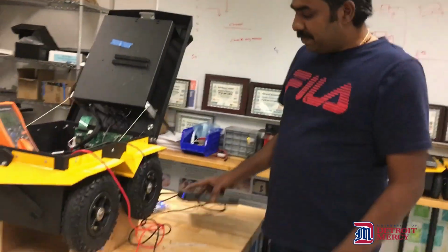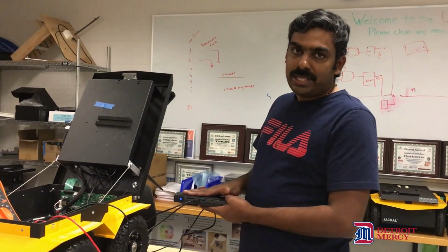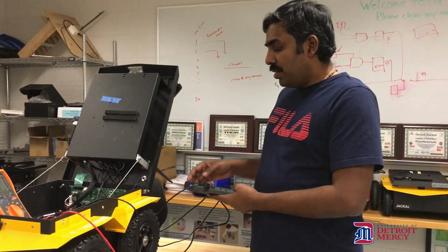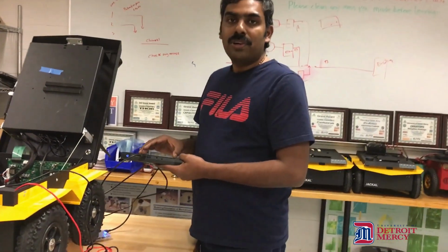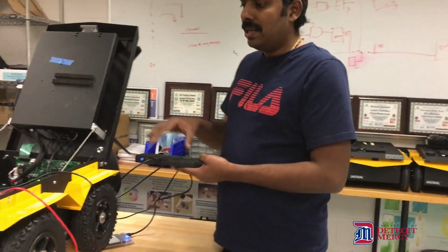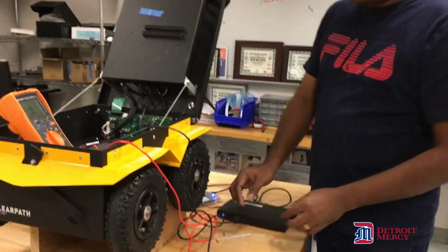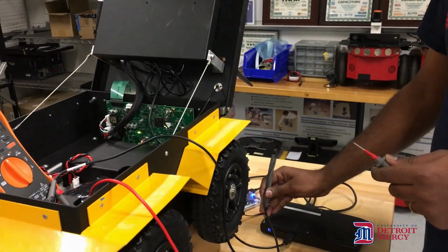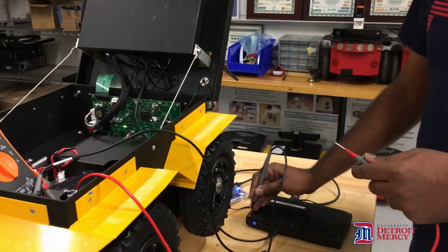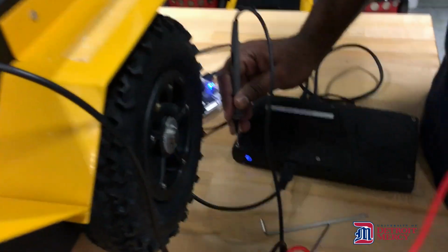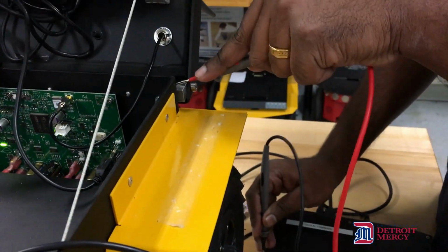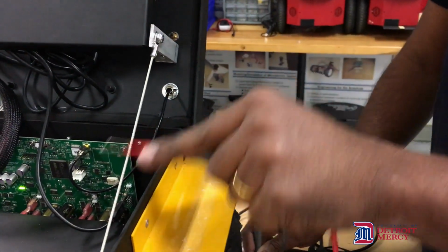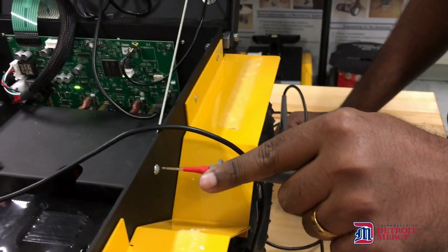So as Karthika explained, this is the NUC computer that we used. In some cases, it can be your laptop. So if you see, there is no common ground between this NUC and the Jackal. I can show you that now. So I have a multimeter here. I'm just connecting the NUC. There's a ground connection here on the NUC chassis, and I connected it. I'm just touching the other end of the multimeter to the Jackal. We can see there is no ground connection here.